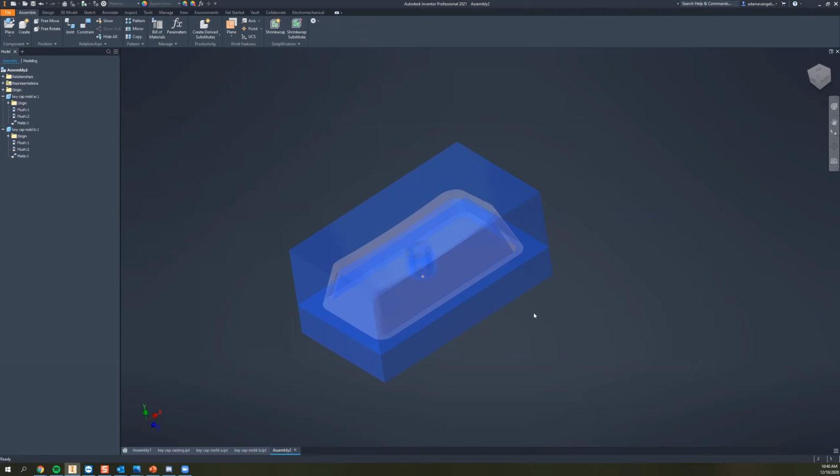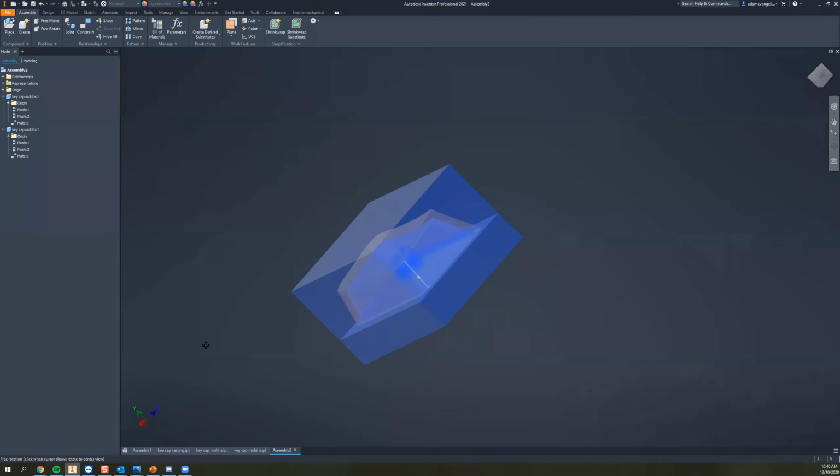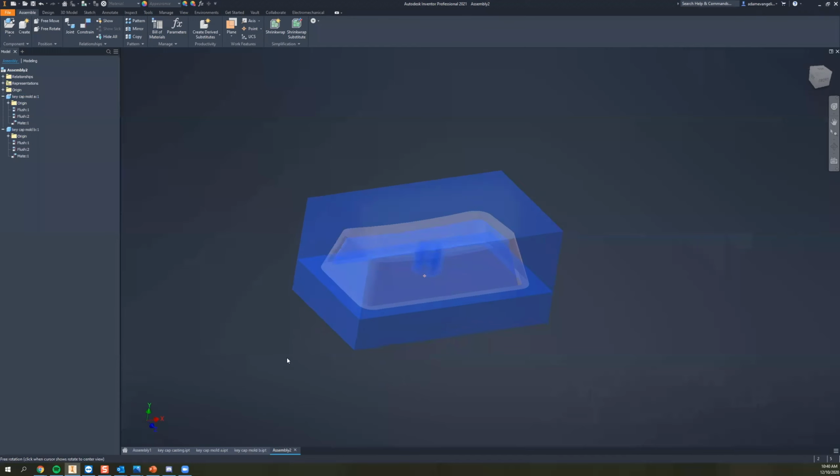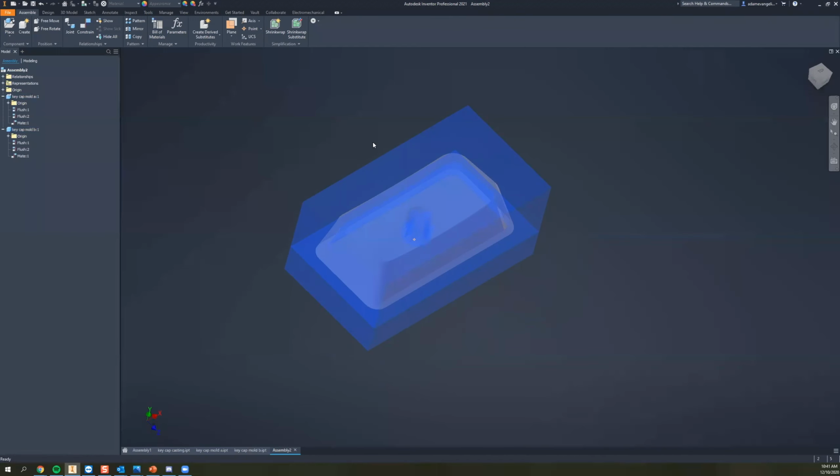When you're looking at it in the sense that it is adding computational overhead, that's correct, right? Because essentially it's referencing two items instead of kind of one, nested in itself. Exactly. So what I do suggest is not doing derives within derives within derives. It's the same thing as don't do iParts within iParts within iParts. That's kind of like XRefs in AutoCAD as well. Exactly. Yeah. So don't go super deep. Don't try to play Inception with your derived parts.